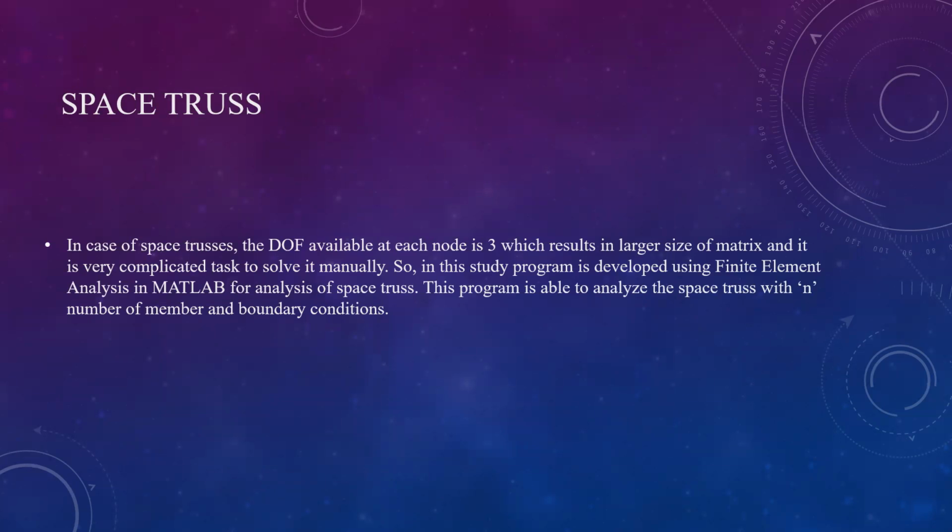Space trusses. In the case of space trusses, the DOF available at each node is 3, which results in a larger size of matrix, and it is a very complicated task to solve manually. So in this study, a program is developed using finite element analysis in Matlab for the analysis of space trusses. This program is able to analyze a space truss with n number of members and boundary conditions.